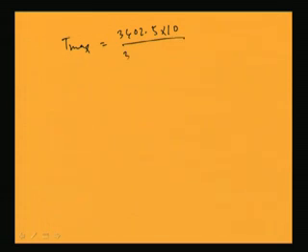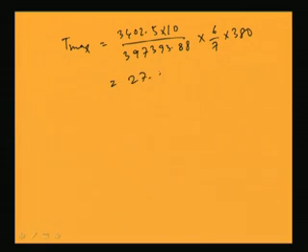So, T max will be 3402.5 into, this is kilonewton centimeter, if I make it into millimeter, I can multiply by 10, then summation y square is 397,393.88 into y max, which means 6 by 7 of h, means 380. So, from this calculation we will get the value as 27.9 kilonewton.